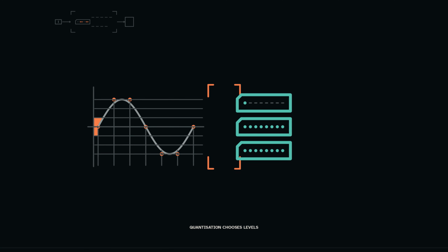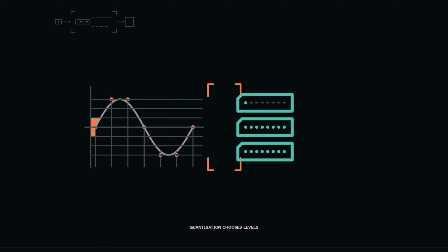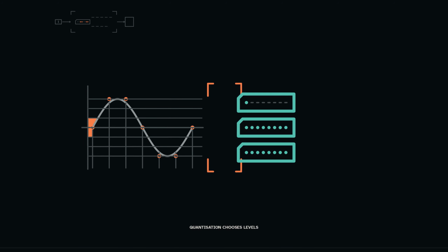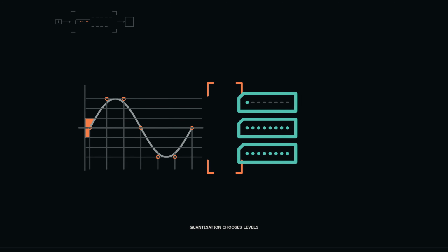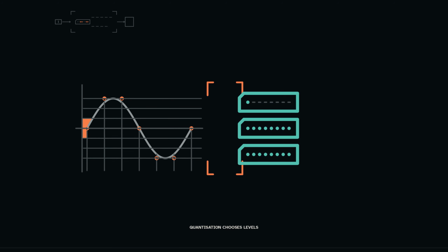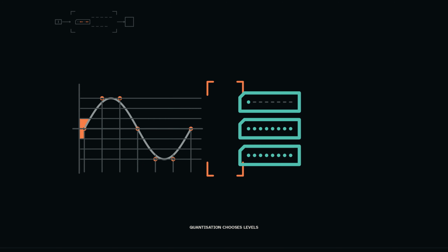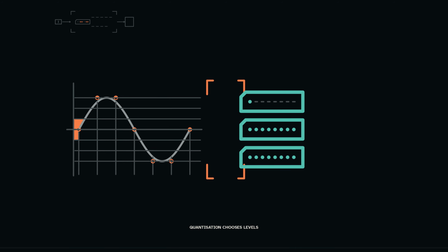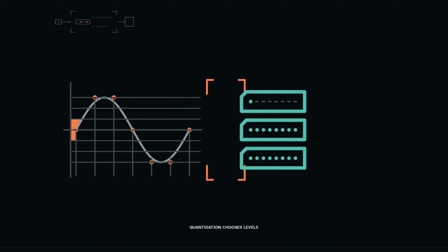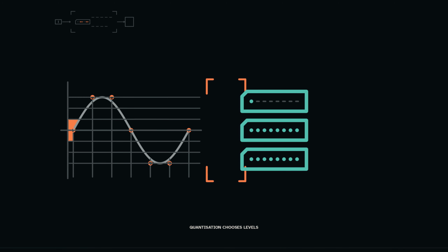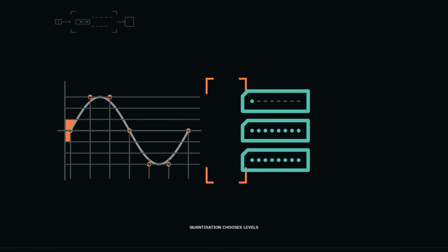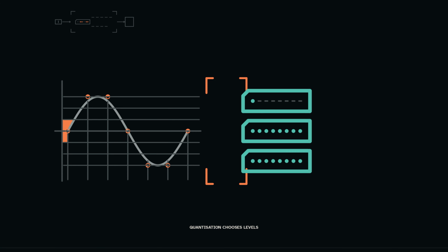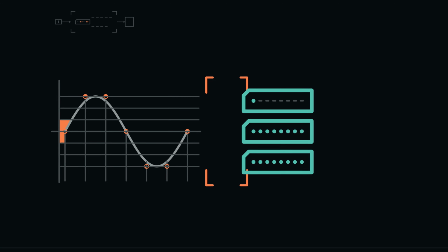Here are two different changing signals and a sparse set of sample times. At every marked instant, both signals cross the same value. What sample sequence will the converter produce? The same one. From those samples alone, the receiver cannot know which of the two unsampled paths occurred. This ambiguity is aliasing. A suitable input filter and a sample rate chosen for the signal bandwidth are part of the measurement contract, not optional decoration added after conversion.